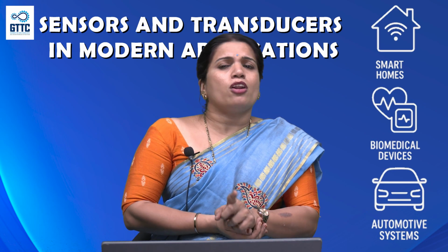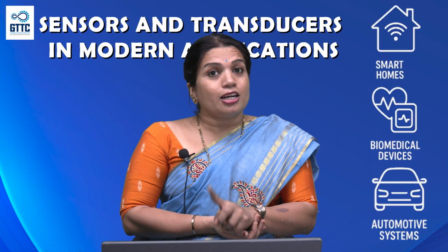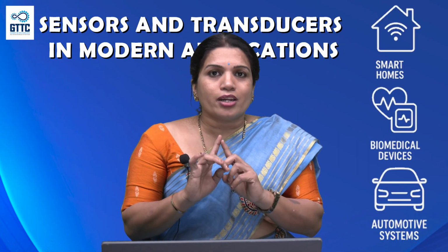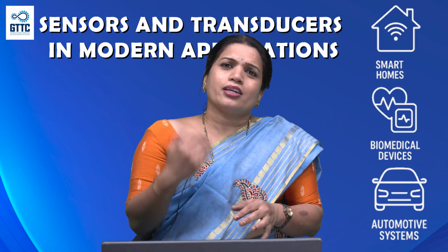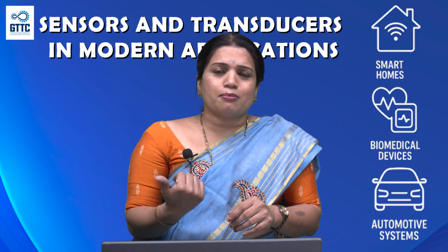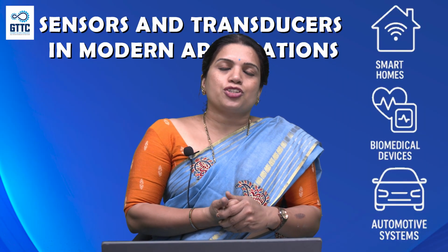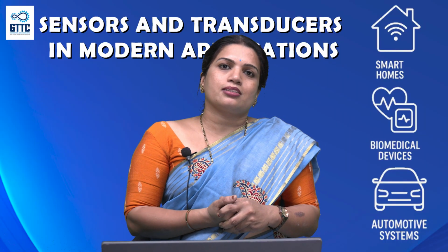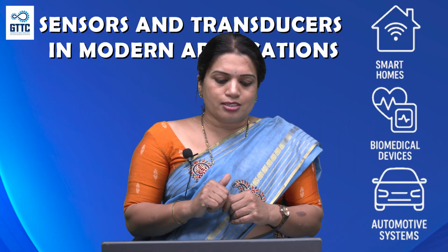Output can be digital or analog in the IR sensor, but in ultrasonic sensors we have only digital, and cost is comparatively less in the IR sensor than the ultrasonic sensor. And detection of light happens in the IR sensor, detection of sound happens in the ultrasonic sensors.